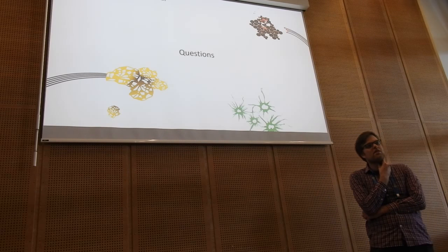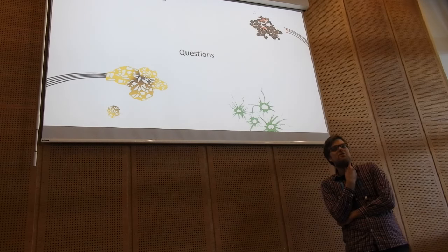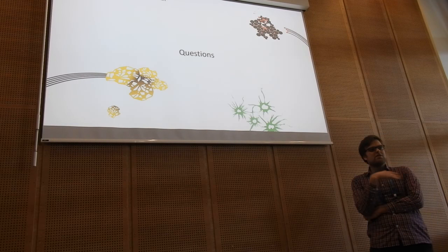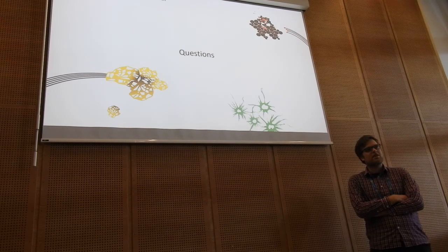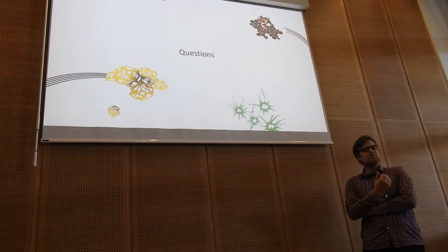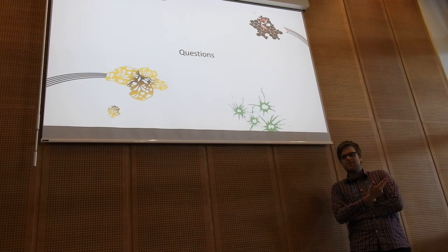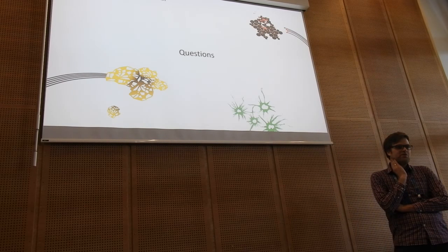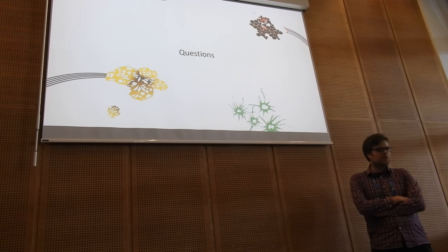It took a long time to calibrate; in total, I ran it maybe between 30 and 40 times to get a full scope of what the model did for various parameter combinations. I calibrated mainly for the infiltration rates and the soil depth, which I went to measure personally, and the internal friction angle, which was from literature.